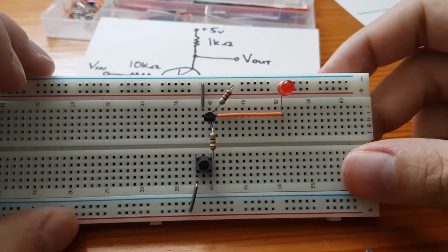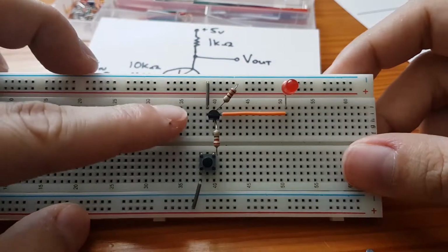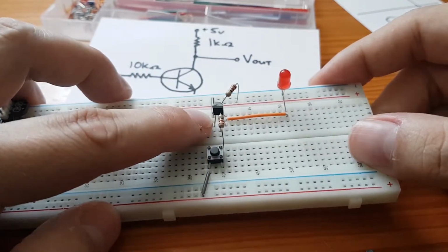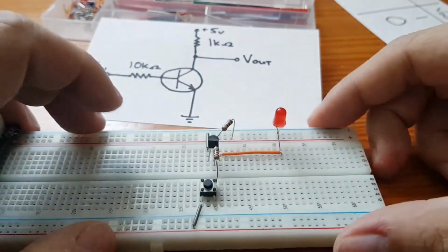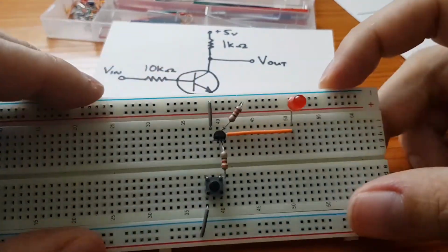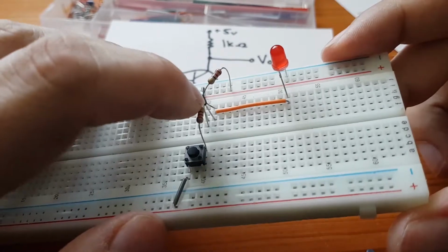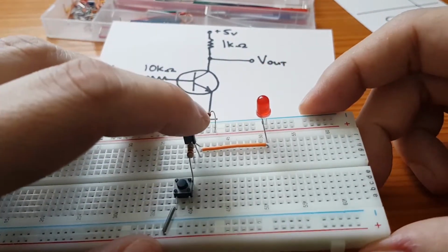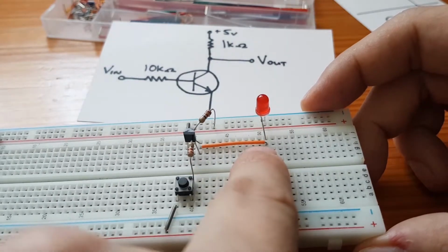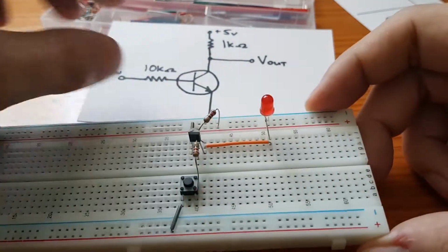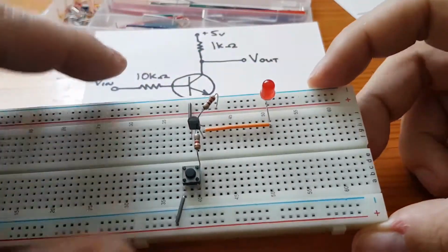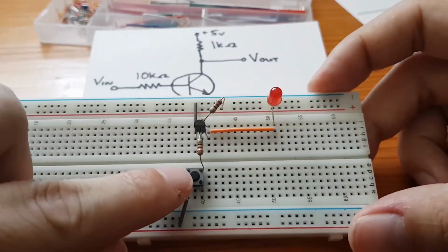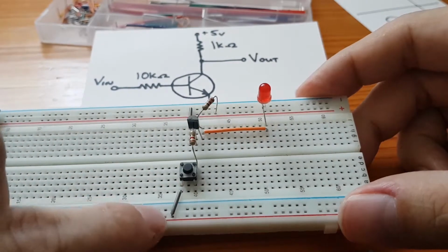Okay, so here is our inverter built on a breadboard. As you can see, we've got our transistor here. What we've done is we've connected the emitter of the transistor to the negative power rail, just like in this diagram here. We've connected the collector, which is this leg on the far right here, to the positive rail via a current limiting resistor, and we have our output jutting out to the side here. So you can see it's the same as that. And finally the base, which is in the middle, we've connected via current limiting resistor to this little tactile switch, which is connected to 5 volts.